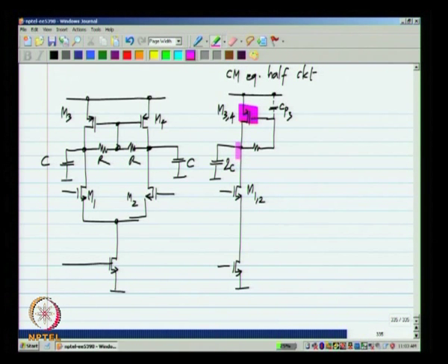So, this transistor and these capacitors behave like an integrator, and this resistance in combination with CP3 will be a parasitic delay, which can be reduced by adding a capacitor Cz. Okay. Now, because we have one integrator and a single parasitic pole, it is quite easy to stabilize this one, okay, compared to the other case where we had a 2-stage op amp.